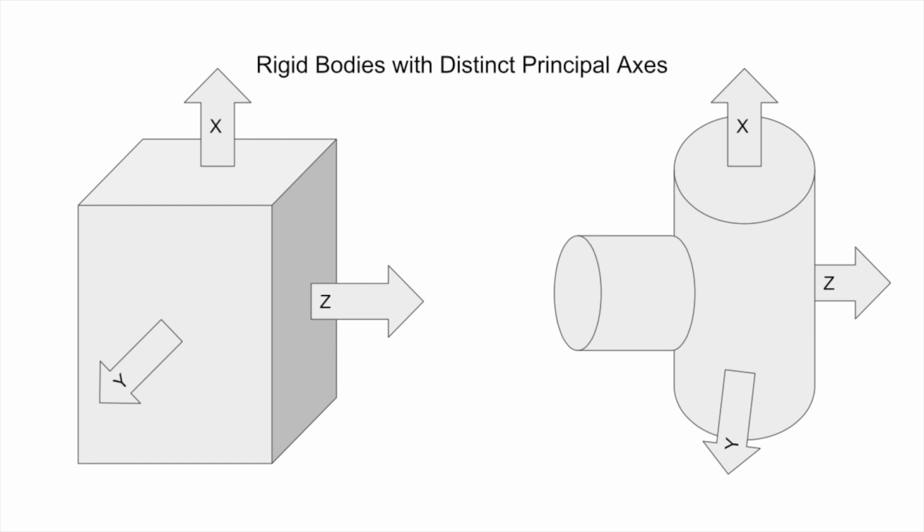Upon viewing the video, we can see that the axis that lies along the smaller part of the handle must be the intermediate axis. We can calculate the moment of inertia of the T-handle by treating the handle as two cylinders and summing the axial components of each cylinder. Before doing this, however, we will need to calculate the center of mass position.